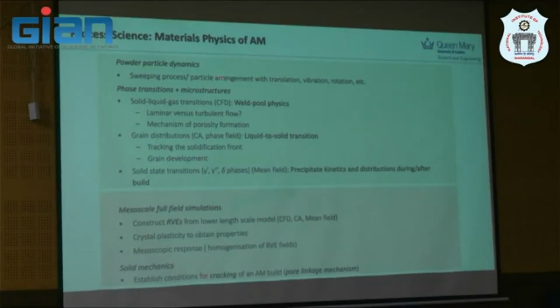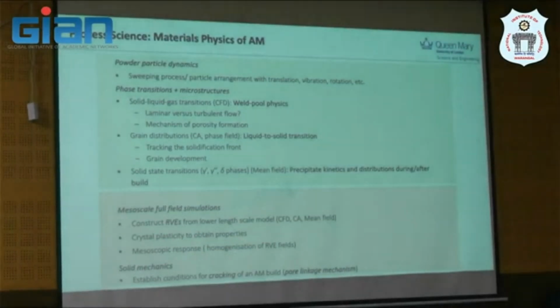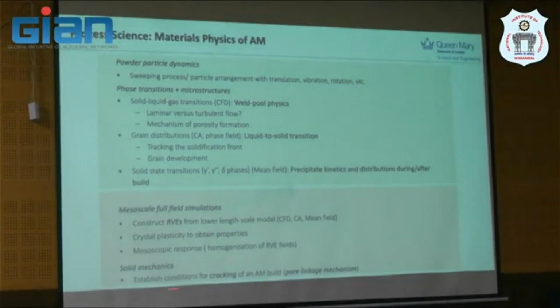This needs to link to what we call mesoscale full field simulation, where you may use different approaches like the representative volume element approach to link all information here to get macroscopic response for the component level calculation, for example. And this can be used to establish the failure criteria in additive. Again, each individual bit here probably means a different group around the world.